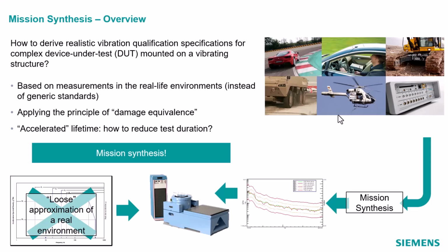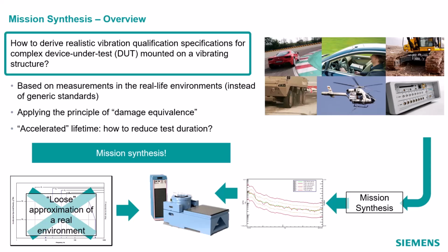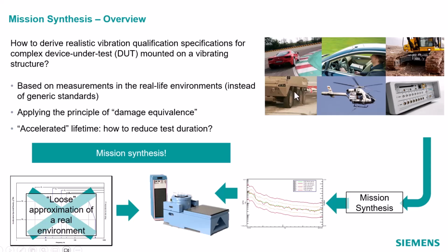It's an important part of vibration testing where we want to derive some sort of realistic vibration qualification test for a complex device under test mounted on a vibrating structure. All of these different components that we might design, we want to design them to meet a service life, and they may fail in the field due to a fatigue failure caused by vibration.